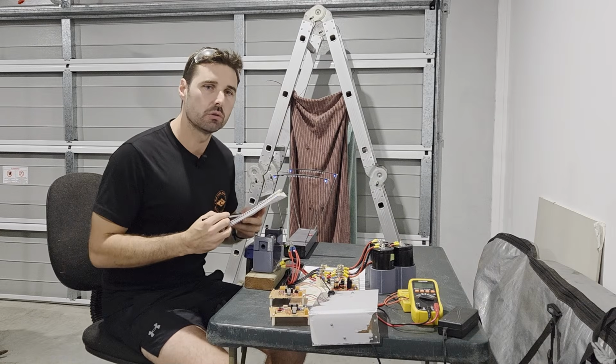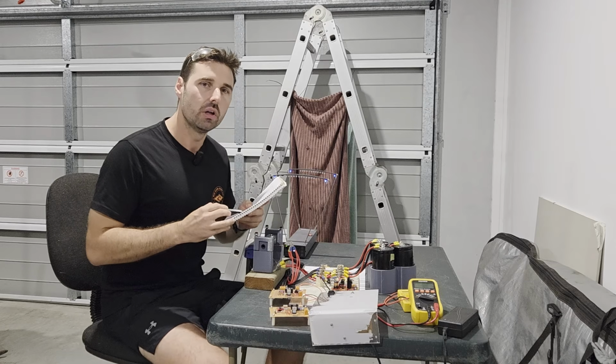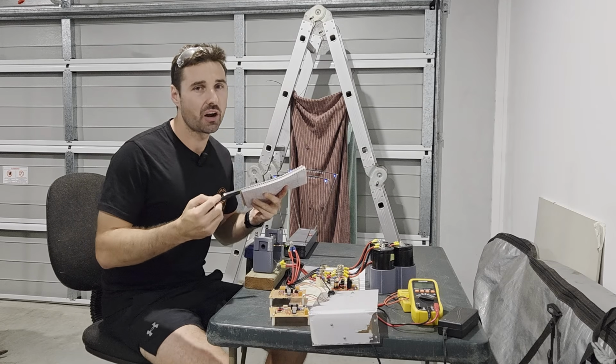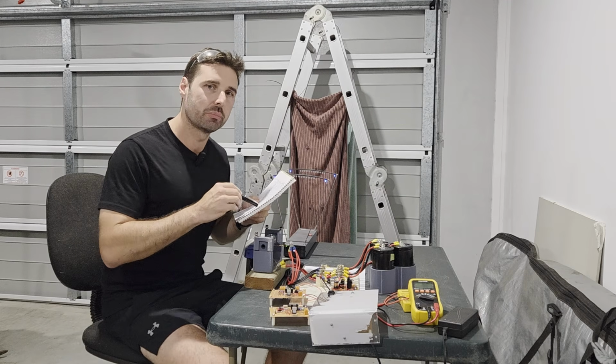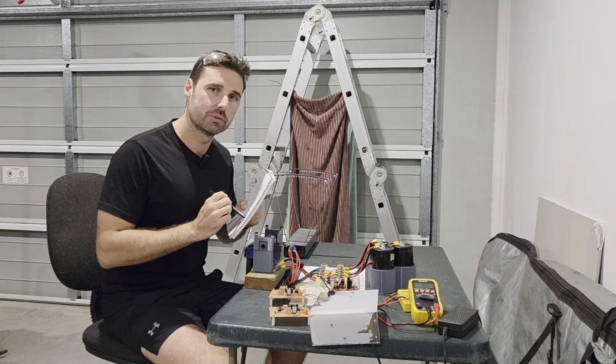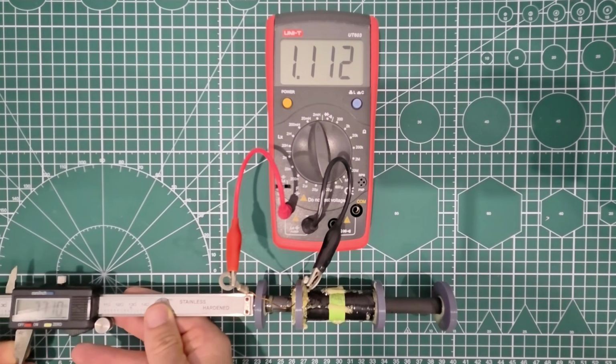After collecting these results, this now gives us the values and information required to build a model of each system so we can see how the current, and therefore magnetomotive force, changes throughout the firing period of the different coil setups. To start with, we need to create a function for how the inductance of the coil changes depending on the position of the projectile.